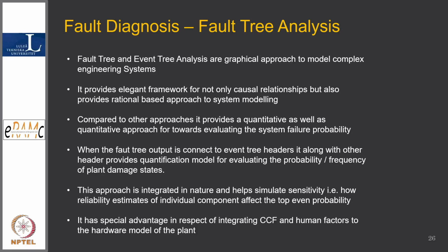It is up to the analyst to assume in a fault tree what the basic component is. Basic component means where the fault tree ends, the last leaf. A diesel generator can be the last node for us, but diesel generators also have many supporting systems like lube oil, starting air system, lube oil system, fuel oil system, control systems, and breaker systems.